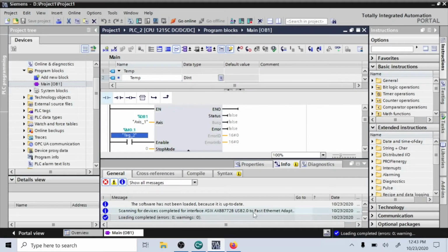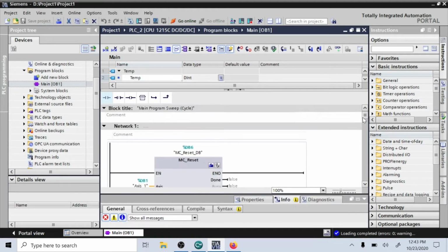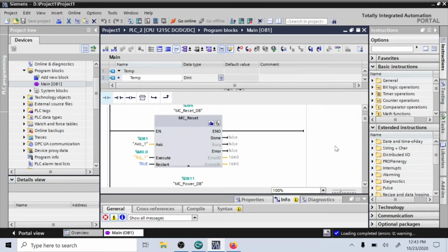Okay, so here is the program in the program controller. And I want to review it for you for a couple of minutes. And then we're going to go through and we're going to go online. And then we're going to bring up the HMI panel. I'm going to show you how I did the HMI panel. So instead of the way that it was done in the one that you're given on the web, I changed these bits from I's to M's.